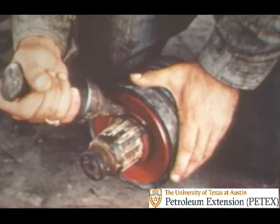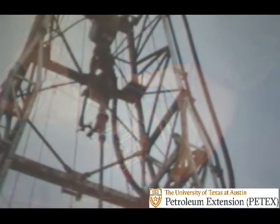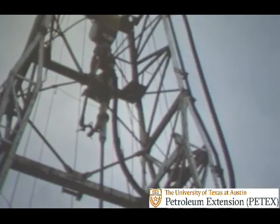Other precautions should be taken when using an oil mud. Here, oil-resistant piston rubbers are being installed before the pump is put into service. Also, the valve rubbers of the pump should be oil-resistant. All other rubber components should be oil-resistant. For example, the rotary hose, the U-shaped line that carries mud from the standpipe at right to the swivel at center.